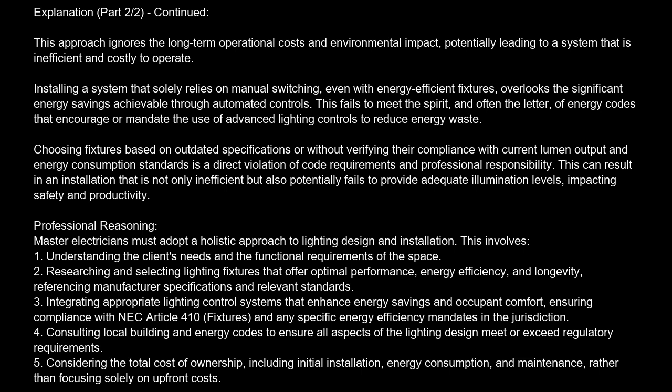Choosing fixtures based on outdated specifications, or without verifying their compliance with current lumen output and energy consumption standards, is a direct violation of code requirements and professional responsibility. This can result in an installation that is not only inefficient, but also potentially fails to provide adequate illumination levels, impacting safety and productivity. Professional reasoning.